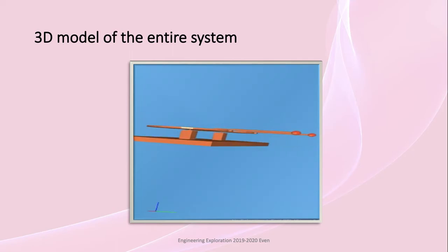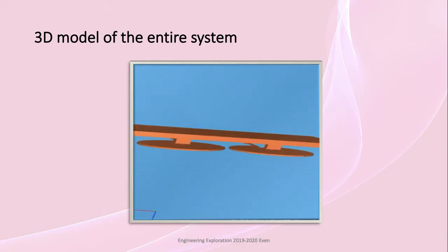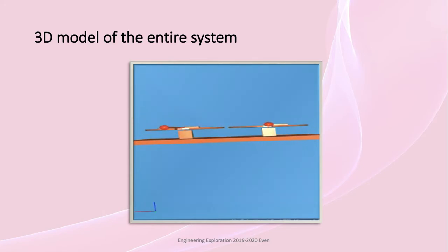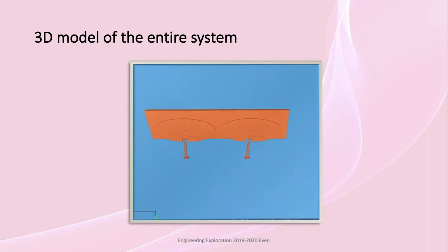The 2 metal servos will control the movement of arms sideways. On top of the metal servo are the circular discs to which toy servos are mounted. These toy servos are directly connected to the mallets. These will control the up and down movement of the mallets.